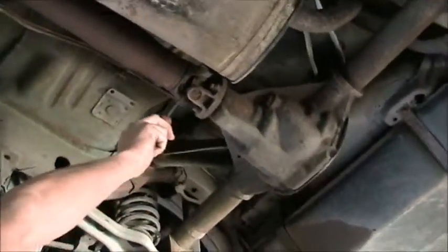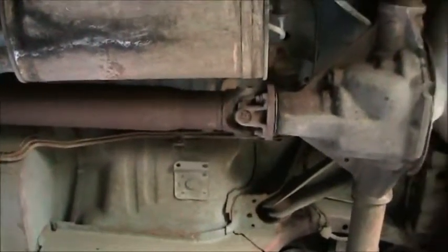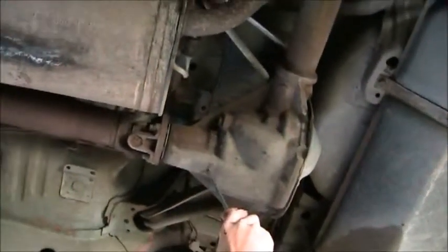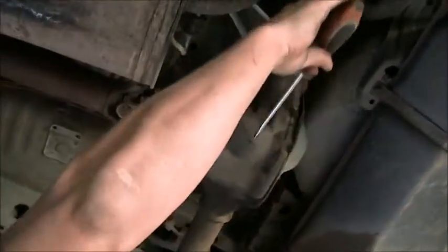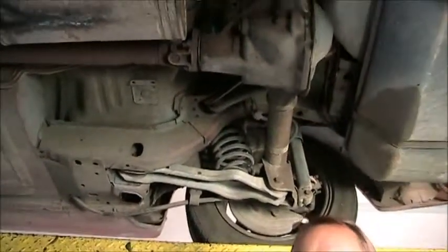In the back we have another U-joint. The U-joint allows the angle of the drive line to change as the rear end is moving up and down when you drive down the road. As well as, now we're to a rear differential. Rear differential on a rear wheel drive vehicle is going to be the same as a pickup truck. We have an input pinion gear, a ring gear, differential gears connected to axles. Again, it turns the power from rotating this direction along the length of the vehicle out to the axles to the direction the tires turn. That's the purpose of the rear end. The differential allows the tires to go different speeds or different distances as you turn a corner.